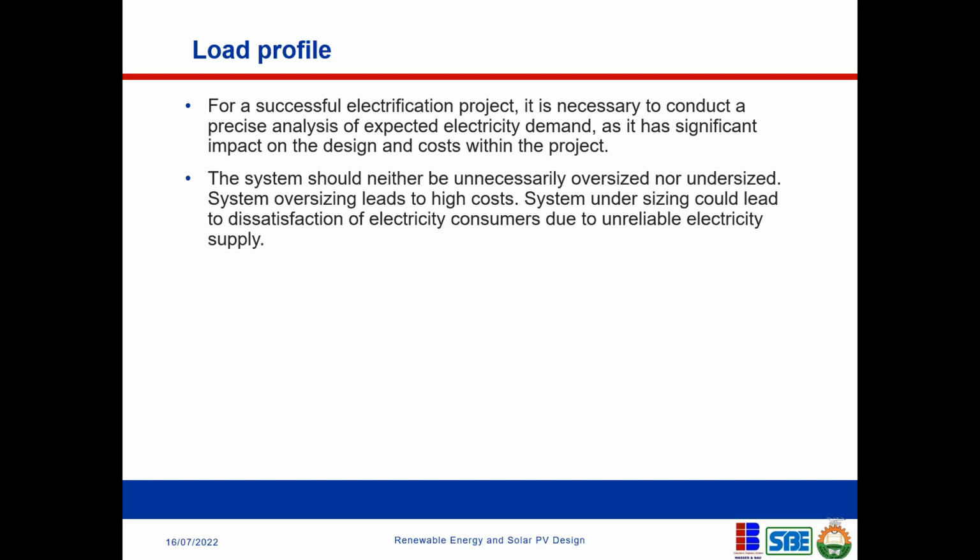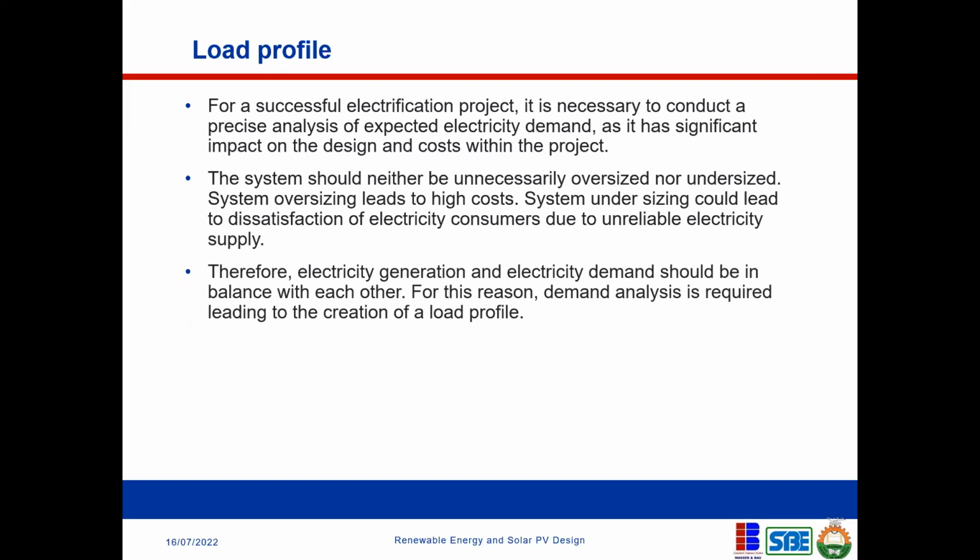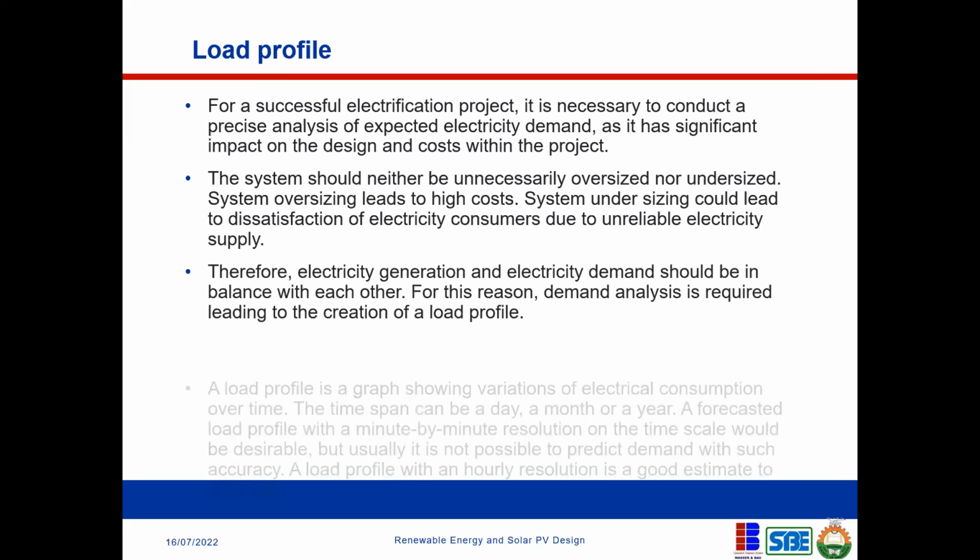And for you to do this proper sizing, you need to have a load profile. What does the customer want to power? For how long does he want to power it? What is the power requirement of this load? If you have it, you can establish a load profile. In our next class, we are going to go through examples of how you can establish a load profile and then determine what size of systems to recommend. We'll do all of that in our subsequent classes. But the important thing here is that you need to have a load profile. That's the most important thing.